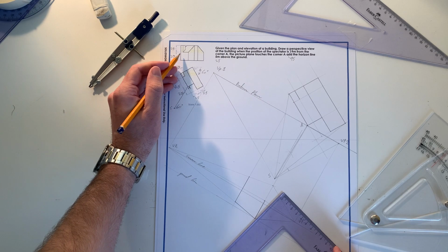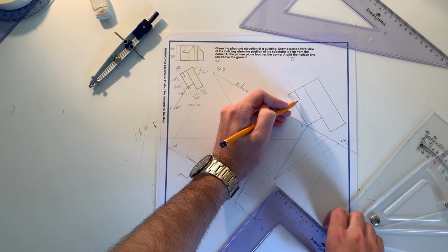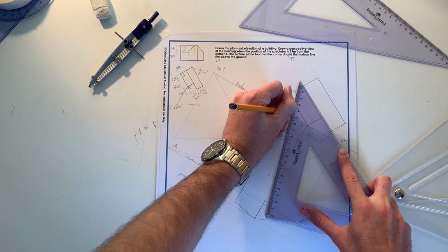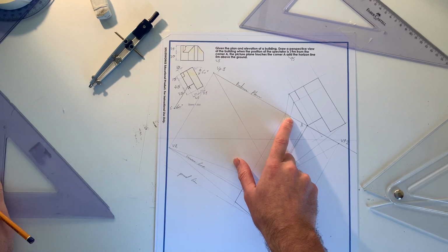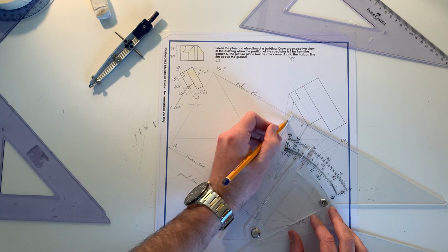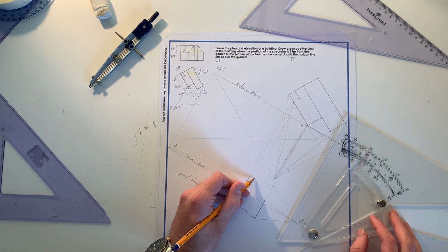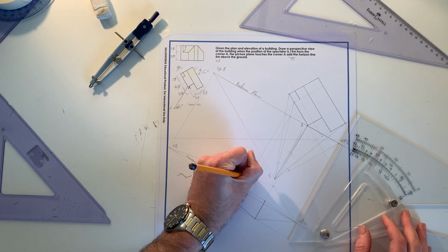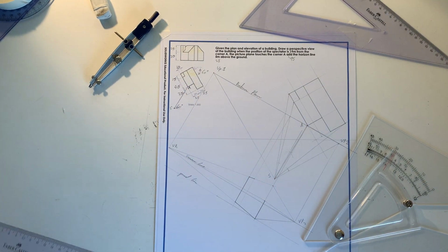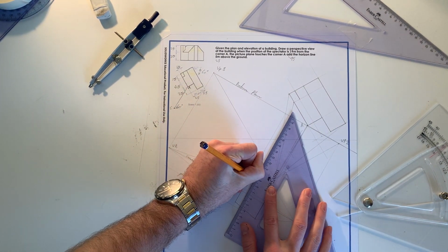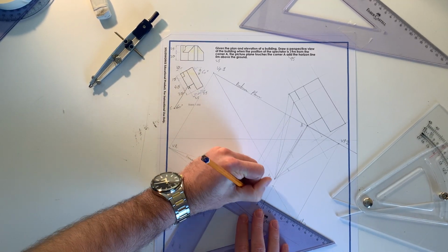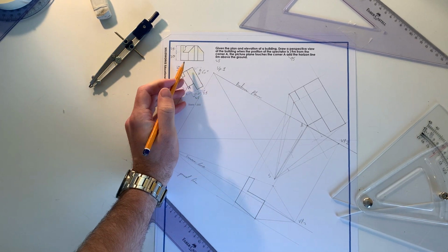So now what I'm trying to locate is this corner above here. To locate that, again, I join him back to my spectator, like so. And where he intersects here in my picture plane again, I drop him down, perpendicular, like so. Where that intersects is that point there. So I can draw that line in. And now I can just complete off that surface from there back to here. And now what I've completed is that L shape here for this surface.